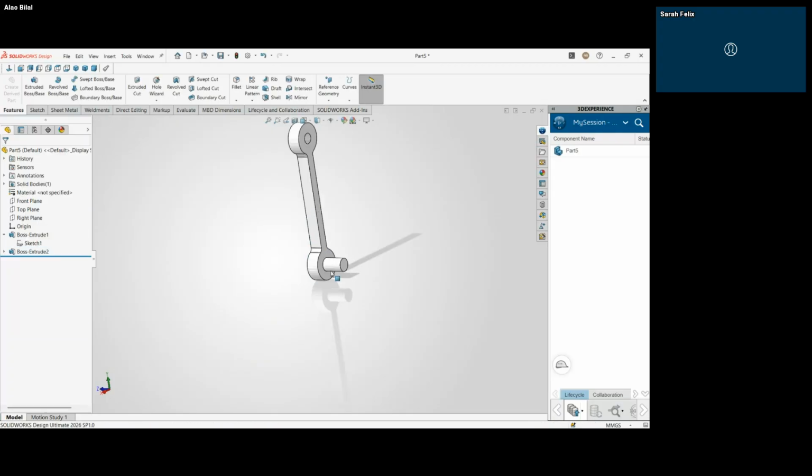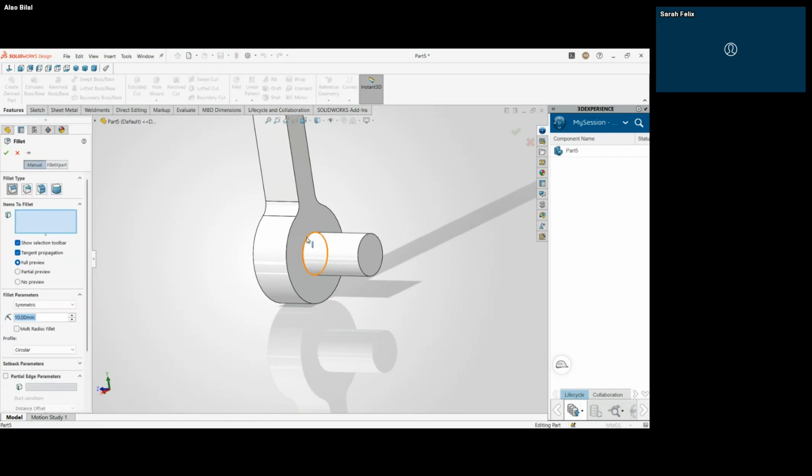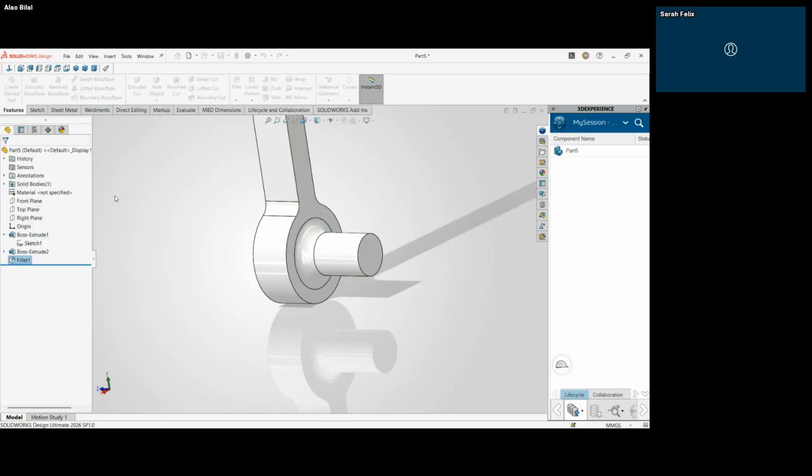So we are putting a fillet of 2 mm at this face here. So we come here, filleting this edge 2 mm. Radius 2. So click on 2 here, and then you are done with this fillet.